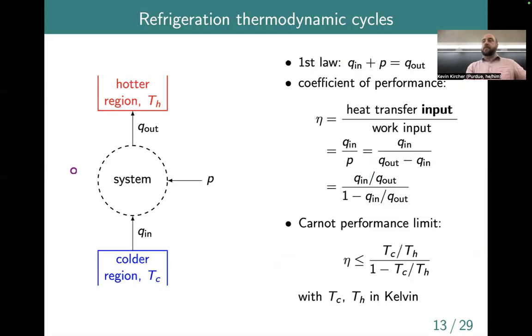Yes. We're using the refrigeration cycle model to model air conditioning. Would we have to change it based on where our compressor is located, whether it's inside the house or outside of the house? Because wouldn't it be kind of a parasitic load on the Qin if it's inside the house? Yeah, so the question is, if we're using a vapor compression cycle to do air conditioning, would we have to model it differently if the compressor is inside versus outside? Because it can be kind of a parasitic load if it's inside of the house. Basically, that machine is not perfectly efficient. It's giving off waste heat, and that would add to the cooling load of the house if it's inside the home. I guess so, yeah.